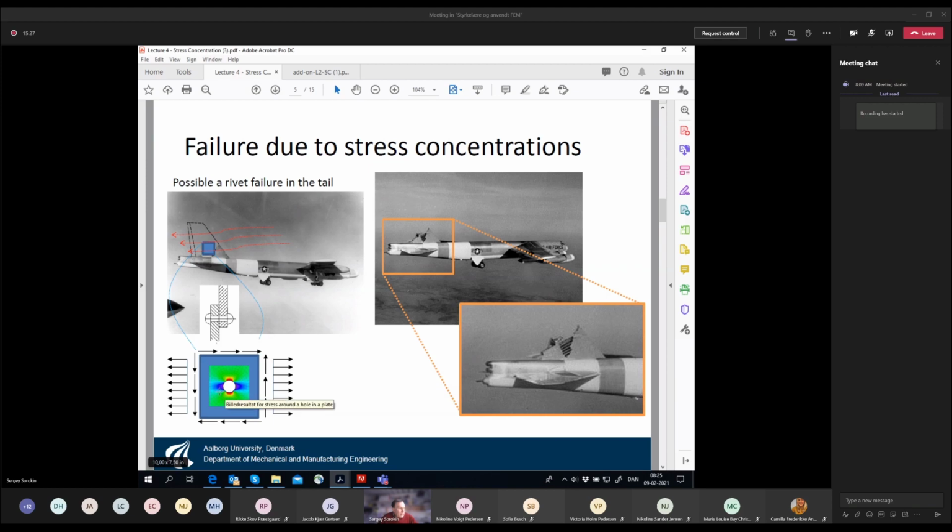And then you see that if you do the cross section, if you chop the specimen relatively far from this hole, then you see it's more or less the same color, sort of greenish. Then if you come a bit closer and you chop it here, then you have these green areas, and also this blue area, which means that you have very low stresses here. I think intuitively it's quite clear, because if you come very close to this hole, then obviously the axial stress here will be just zero.